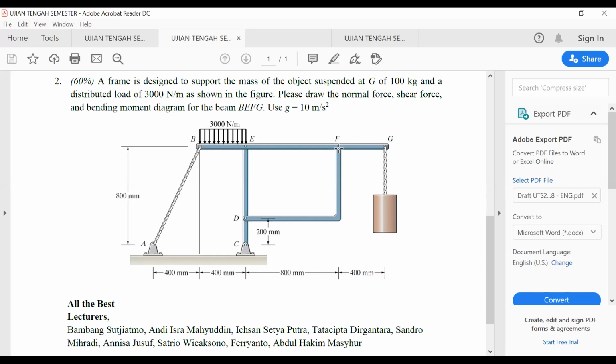So in that case, you have to draw the free body diagram of CDE as well. At CDE, there are 2 forces at E, EX and EY, 1 force at D, FDF, and 2 forces at C, CX and CY.